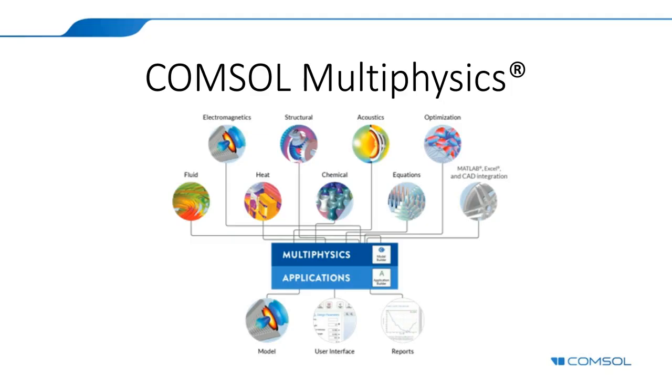That is very important. For some applications, you have to be able to use your data. It could be temperature-dependent materials or a particular structure mechanics model. You can also optimize, and very important, you can integrate COMSOL with CAD software, so you can import more complex geometry, even if most of the time you're good to go from the beginning with the capabilities that we have in COMSOL to create geometries.